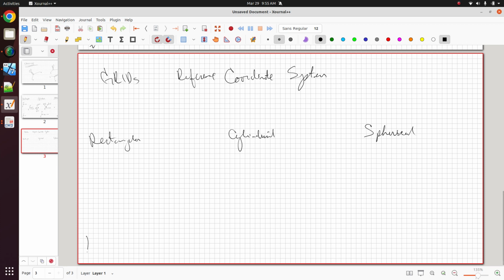So here at the bottom left, we're going to define a coordinate system. So I'll say it's x, y, and then z. And then here, we're going to draw a point. Now, let me manually type up a grid entry. So we'll call it grid 1. Maybe we'll assign this coordinate system a CID of maybe 101. So here we're going to reference the coordinate system, and then we're going to say that the point is located at 1, 1, 0. So 1, 1, 0.